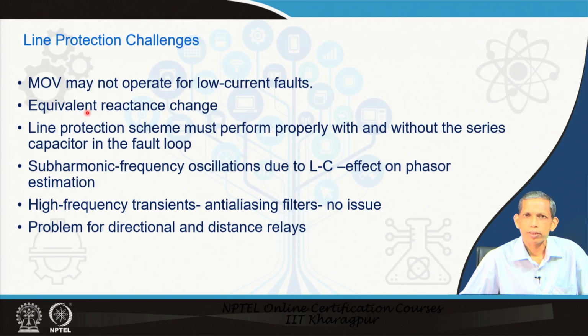When MOV operates, following that the corresponding air gap ignites. These phenomena lead to change in equivalent reactance, and therefore the corresponding current and voltage across the capacitor, and so also at the relay point. Line protection scheme must take care of these operations. So, the capacitor may be there in the circuit and may not be there because of the bypassing by these arrangements.